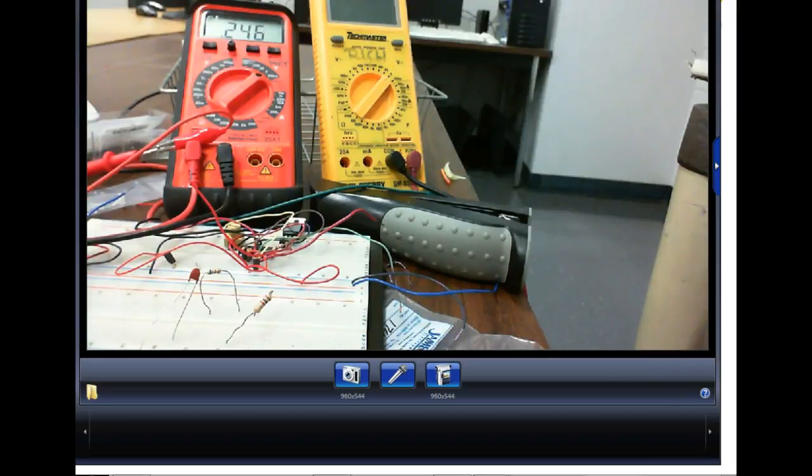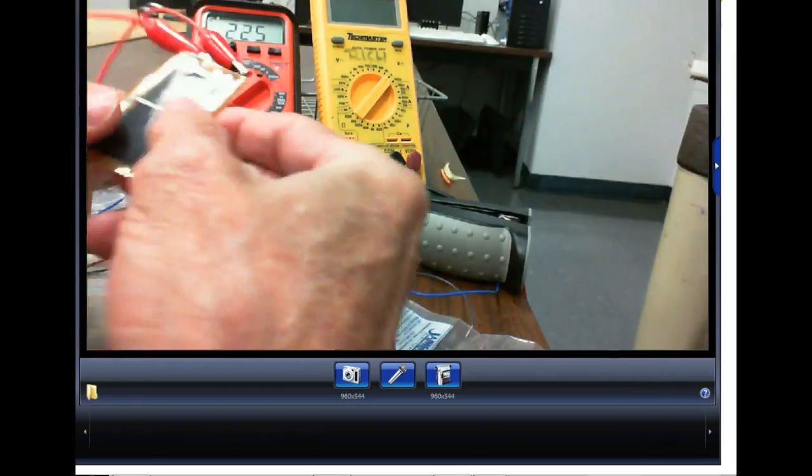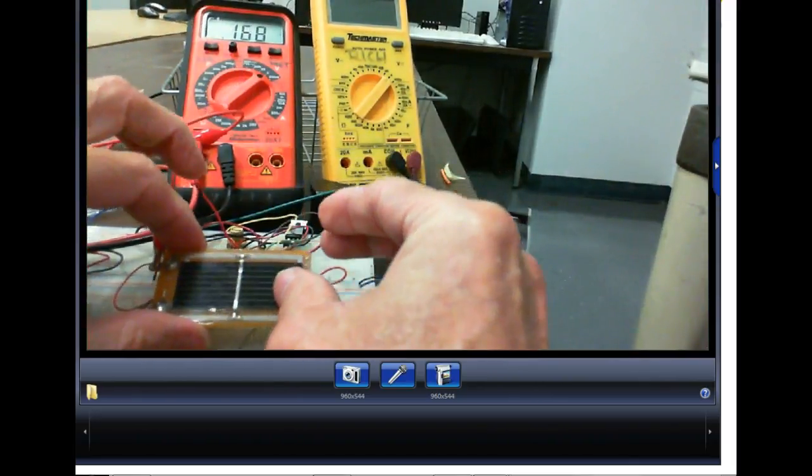So this is what my rope lights on my front deck do. It has a photovoltaic cell on it. And then it's got a little electronic circuit on there. It's got a little NiCad battery in there. A NiCad battery is a rechargeable battery, right? So what does it do during the day? Charges. And when the output drops down to a certain level, the little electronic circuit switches it over to the battery and turns the lights on. So it's using that as a two-fold thing right there.